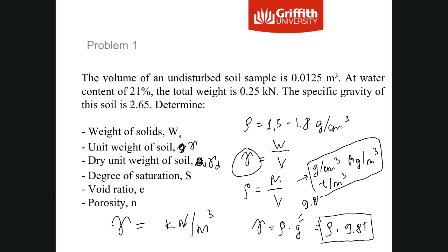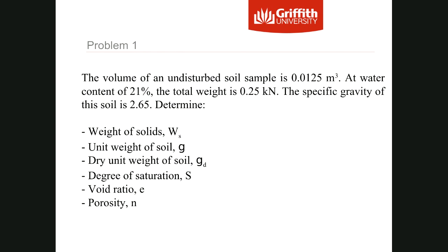Maybe now you feel a little bit not sure about it, but once we start calculating the unit weights, you will see that it's pretty easy if you know density. Just multiply by 9.81. Okay, so I'll remove this one and again change to unit weights.